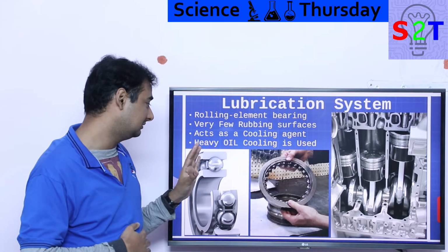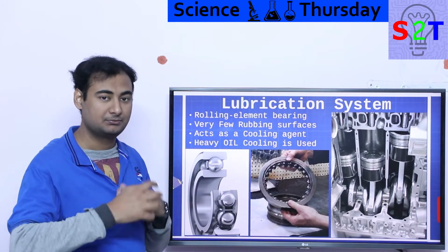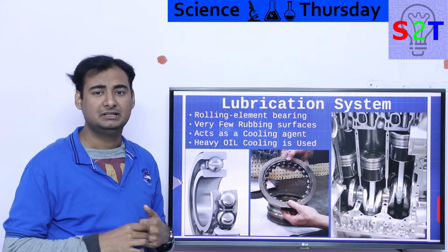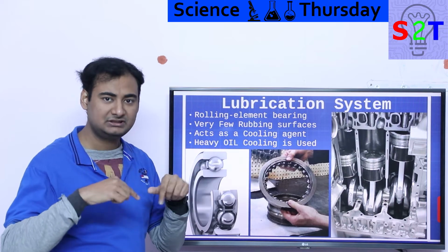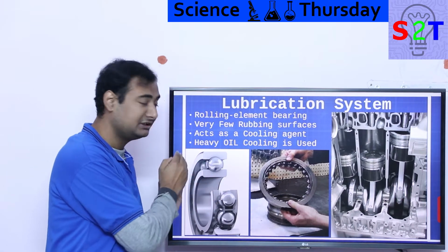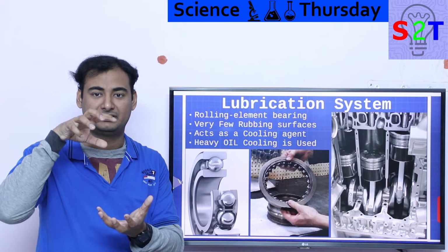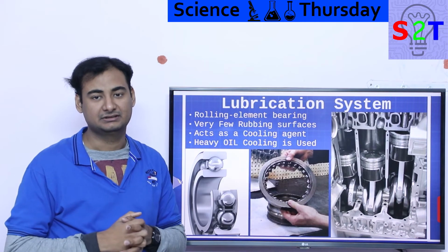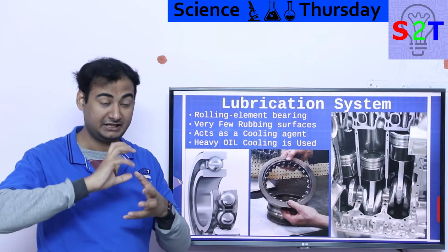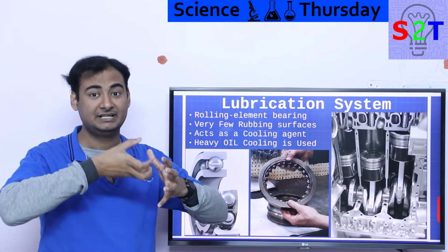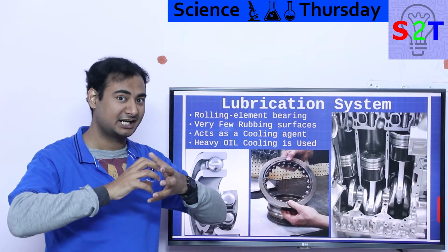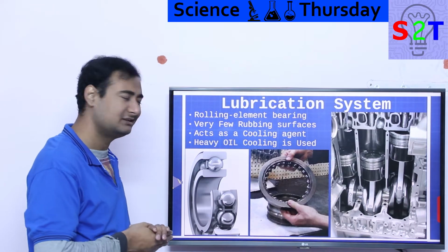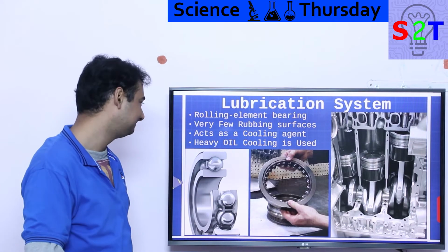Now, heavy oil that is consumed is generally put in a very different way. I have provided the video down below, which is very detailed. The amount of flow these have is huge, because these are generally spray-on. They will rarely dunk anything into oil. It's generally sprayed on, so it reduces the wear and tear, because if your bearing is going through an oil sump, it acts as a drag. You don't want that drag. So the lubrication system is kind of unique in a jet engine. It does not require as much as you would think.